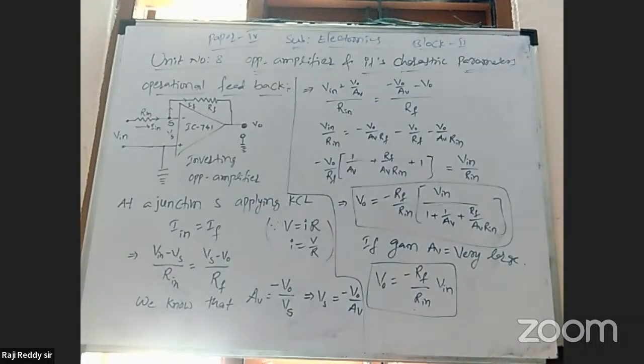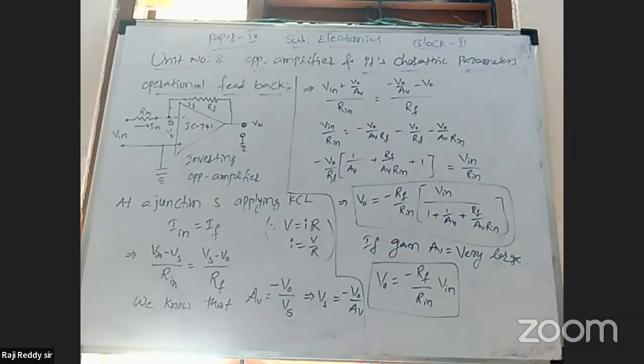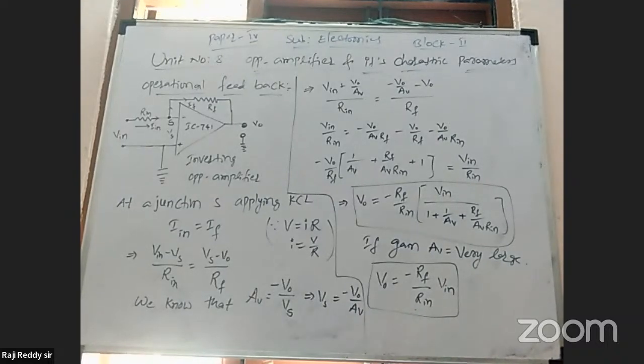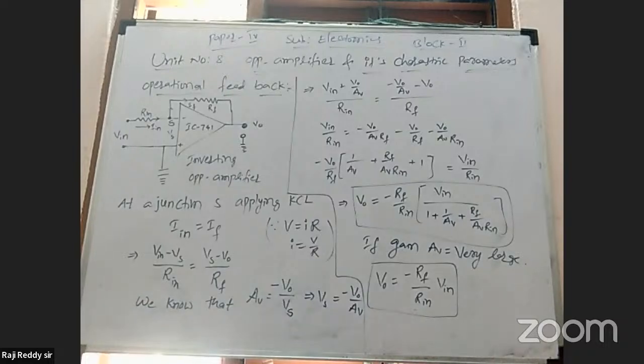So the ideal operational amplifier's internal resistance offered by themselves is zero. That is nothing but, he is saying, input impedance is infinite. No current flows to it. Second point, output impedance is zero, unaffected by the load. The range value is also given.